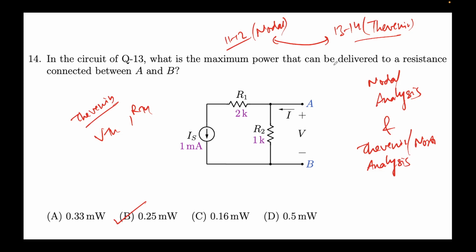I'll pause for a bit over here, and if you have any comments on whatever we have discussed, let me know. I'll just summarize in a few seconds. So till now we have talked about two major things. First was Thevenin and Norton analysis. In the first 4 problems we talked about how we interchangeably convert from Thevenin to Norton and Norton to Thevenin in order to arrive at the final Thevenin equivalent. If we wanted resistances in parallel, we went to the Norton equivalent. If we wanted resistances in series and wanted to add them up, we went to the Thevenin equivalent, and we kept on interchanging them until we arrived at the final Thevenin model. Then after that we solved a couple of problems specifically focused on the principle of superposition.